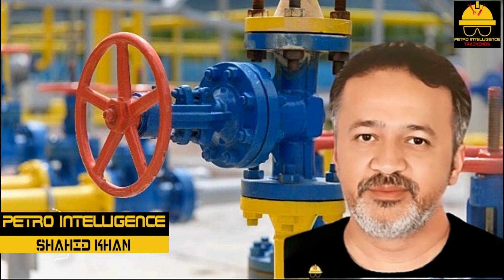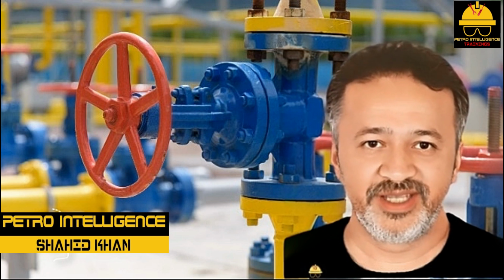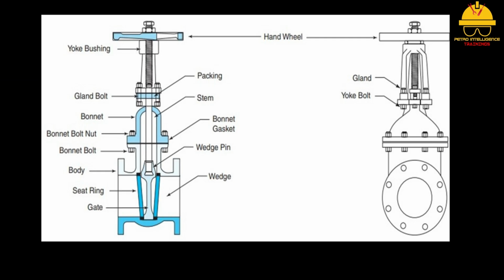The edges of the seats match up with the parallel discs or wedge. The typical gate valve consists of a gate, body, seating area, stem, bonnet, packing, stuffing box, packing gland, and handwheel, as shown in the picture. The gate can be wedge-shaped or may consist of parallel discs. It can be composed of a variety of materials. The gate is placed directly in the path of a process flow when it is shut and is lifted completely out of the way when open.